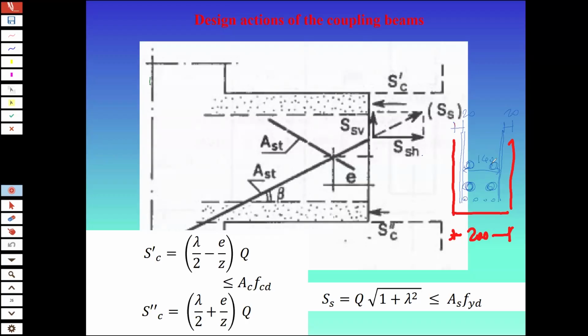If you have 4 bars, put them into this arrangement, but this requires more space. But it can happen because, as we said, this increases with the floor as you go down. So it can happen that you also need another bar in the middle. And what does that mean? Well, it means that from the original 14, you lose 6.